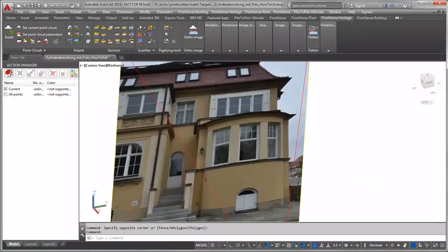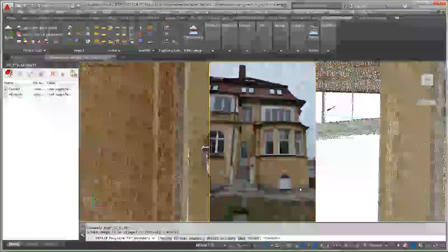And as I'm only interested in this part of the image, I will use the clipping tools for imagery to clip them to this extent, so when unwrapping we will ignore the rest of the photograph. So I go to Clip Image under Image Computation, and now I have to select the image I want to clip, like this one.